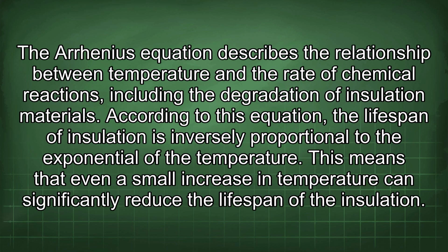The Arrhenius equation describes the relationship between temperature and the rate of chemical reactions, including the degradation of insulation materials. According to this equation, the lifespan of insulation is inversely proportional to the exponential of the temperature. This means that even a small increase in temperature can significantly reduce the lifespan of the insulation.